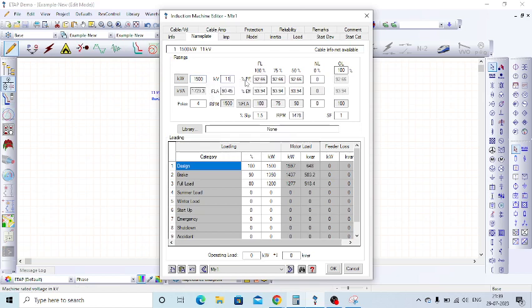So this one will be PF, means power factor. Here FL, 100/75/50, is the loading condition when the motor is operating at 100 percentage load. That time it will draw a 92.66 percentage power factor. So that information we have to update based on the manufacturer data sheet. Then EFF is efficiency in percentage. So here it is 93.94 percentage efficiency for 100 percentage loading, 75 percentage loading, and 50 percentage loading.